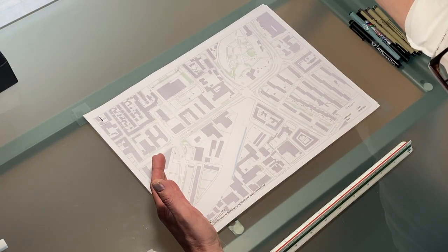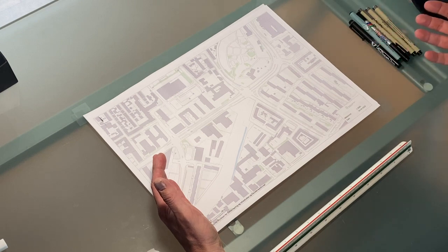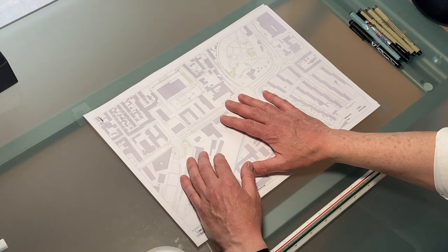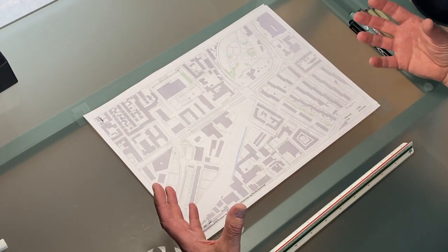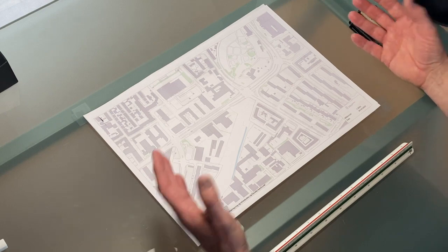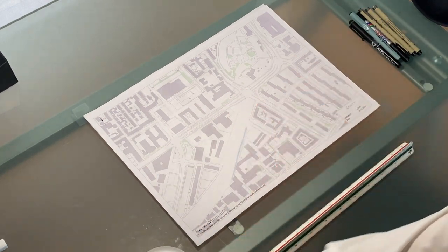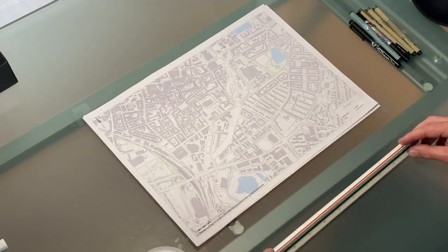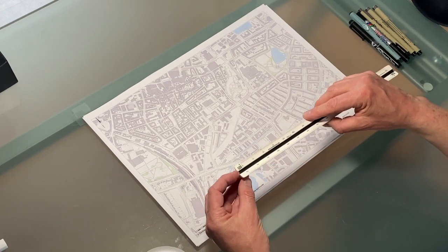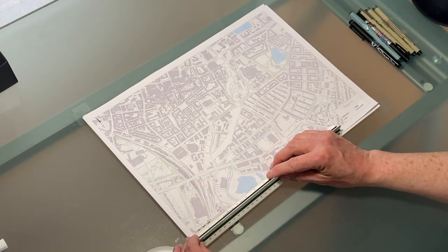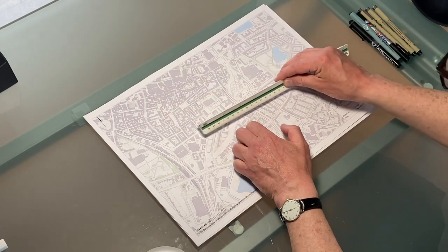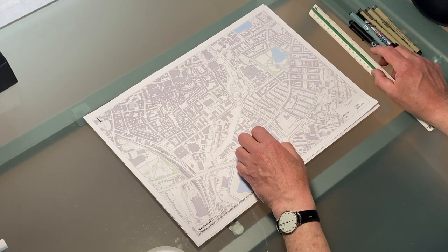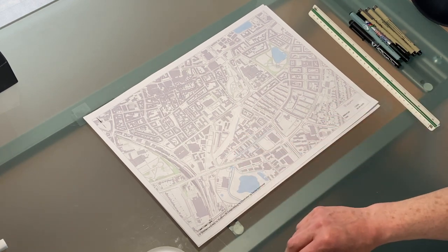You may of course do large scale printing and do larger base maps. You may want that for large master plans and stuff, but mostly what you would prefer would be to go down in scale. And to this end I have also here a third map, which is scale 1 to 5000, and again we want to find the correct scale on the ruler so that we can measure exactly distances, widths and so on.